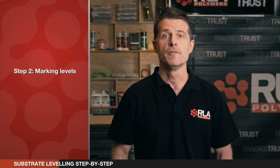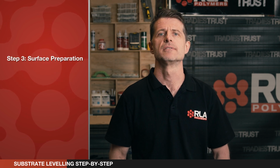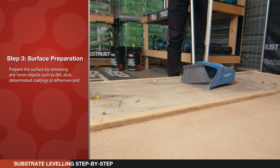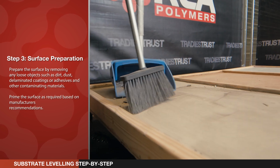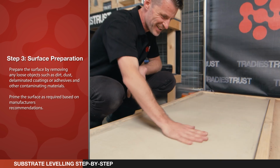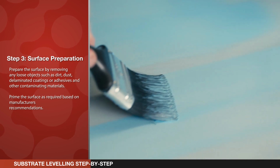Step 2. Marking levels. For floors that need to be raised, mark levels accordingly. Step 3. Surface preparation. Prepare the surface by removing any loose objects such as dirt, dust, delaminated coatings or adhesives, and other contaminating materials. Prime the surface as required based on manufacturer's recommendations.